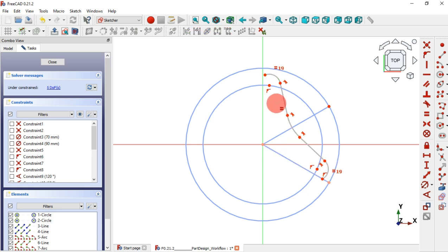The next thing to do is to constrain this point and this vertical axis, this point here and this point here. So how can we do that? To do that, first we need to select this constraint here. Just click on this icon and next select this point, and now this vertical axis, this point here and the vertical axis, and next this center point and this vertical line here. And now I have this and also 2 degrees of freedom. So the next thing to do is to set the radius of this arc and also this arc here. Let's see here in this drawing page.